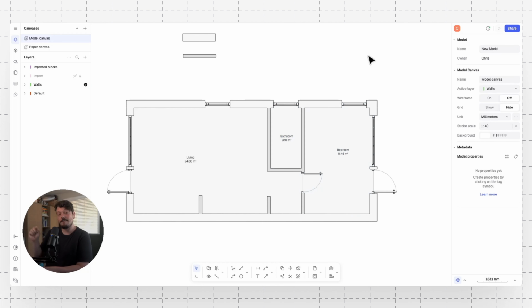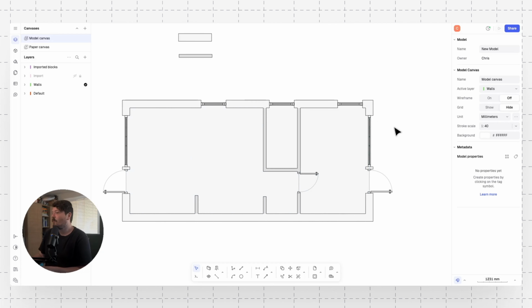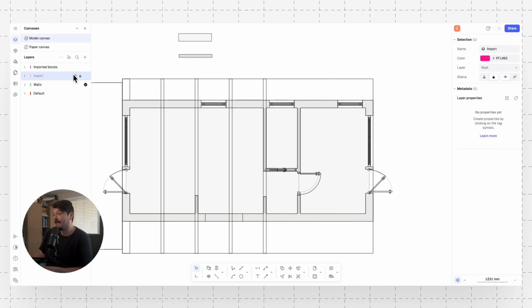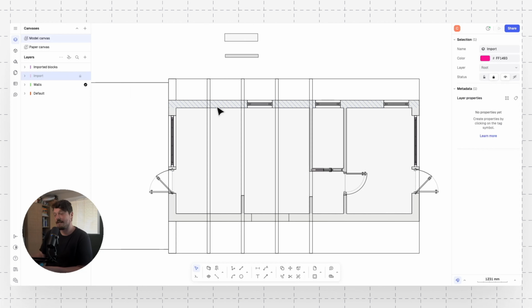These will read the inside line of the walls that we've placed, and they will also automatically calculate the area. Based on the unit you've chosen, it will choose a meter squared or square foot. One more element that I want to show you is the annotation lines.